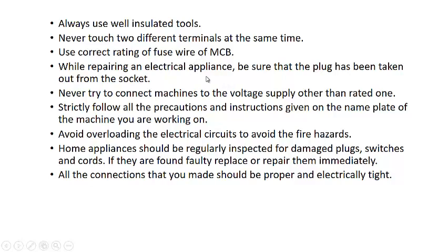In that case, if you use a fuse of lower rating, it may burst or it may fuse before you get the actual power. Or if you use a fuse or MCB of higher rating, it may not trip when there is a short circuit. So you need to have a proper rating of fuse and MCB.